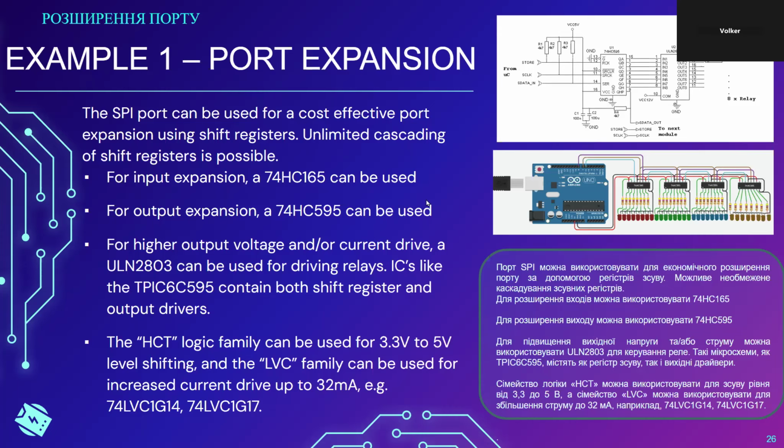A low side driver is essentially just a transistor or a MOSFET. If it's a bipolar transistor, it is connected with the emitter to ground. The base goes to the microcontroller with a current limiting resistor, and the collector is connected to the motor, and then the motor is connected to plus 12 volts.